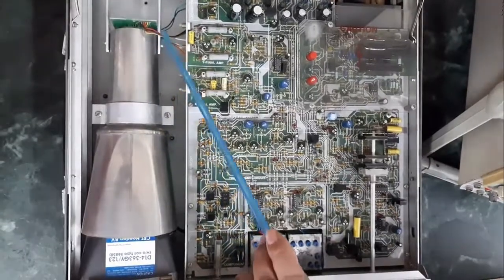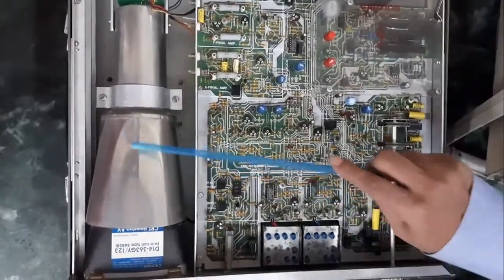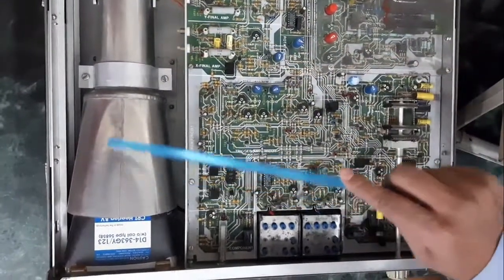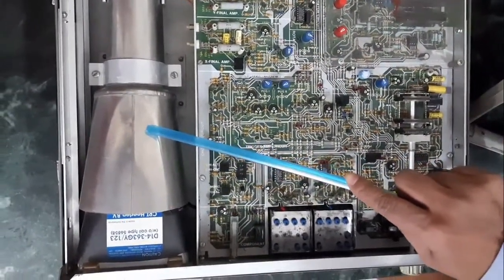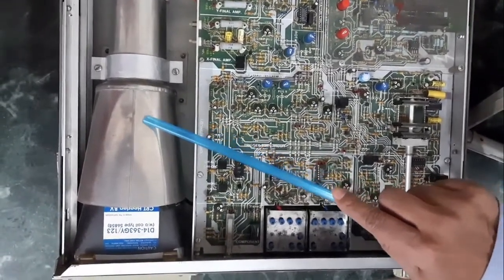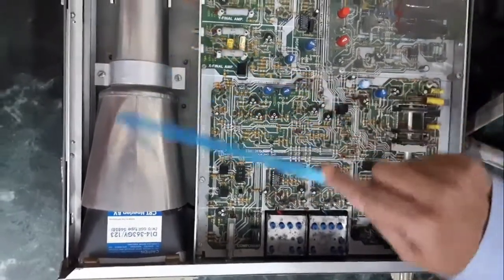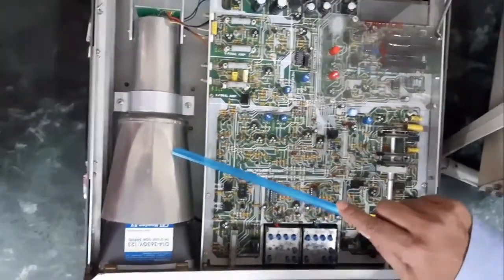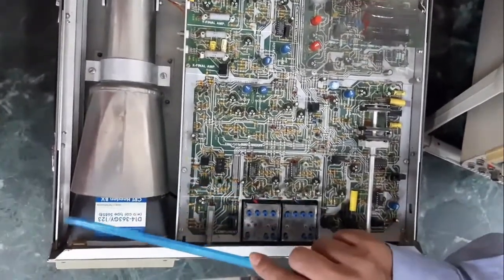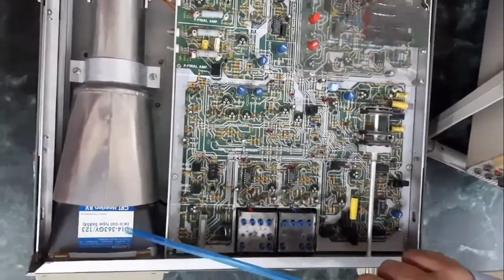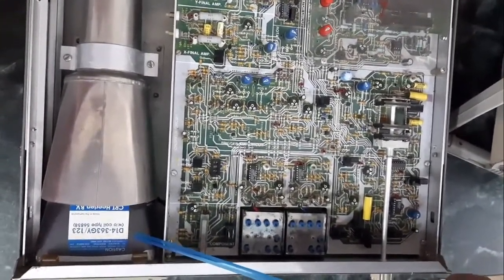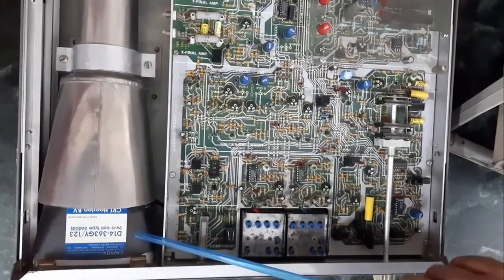So now let's look at the grid here. You are able to observe the shield here. This shield is for protection from electromagnetic interference, which would disturb the operation of the CRO and change the value of the observable voltages. So the shield is here to protect the CRO from electromagnetic interference. The portion covered by the shield, the lower part of this one, is the CRT. That is the main part of the CRO, because without the CRT we are unable to display the signal.